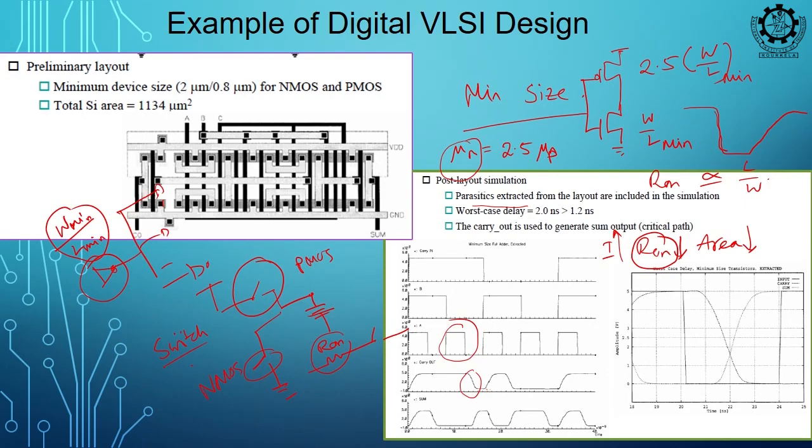So, we just discussed in which mode our resistance is minimum, saturation or linear? Linear. So, that is why in digital logic you will see that my transistor is operating in cutoff when it is off, and in linear mode when it is on. But in analog you want to make an amplifier, you want to make a current source. So, the transistor should be biased in the saturation domain. You are studying analog in this semester, right. So, you will be discussing only saturation. In digital circuits we will be discussing only linear. Okay. So, this is the reason.